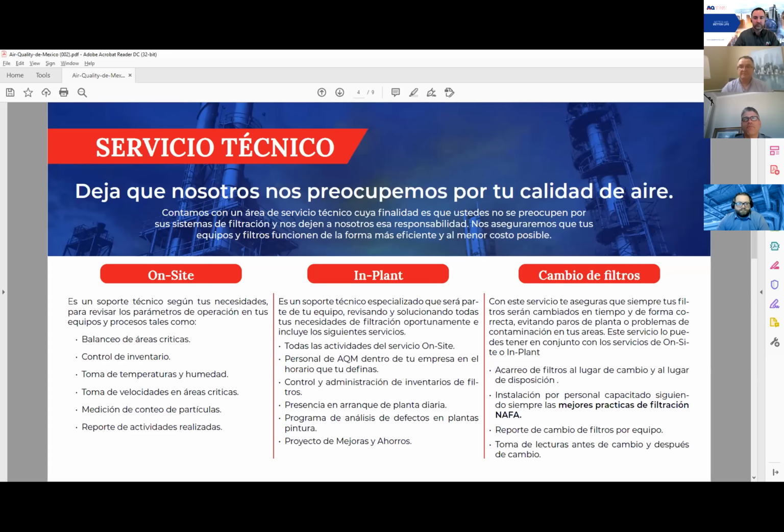I had one of my first applications where they were spraying contact cement, and it's kind of funny, the guy mentions 2 hours. They were changing fiberglass pads out every 2 hours. We went an entire shift with our high cap Super 2, just the roll filter itself.